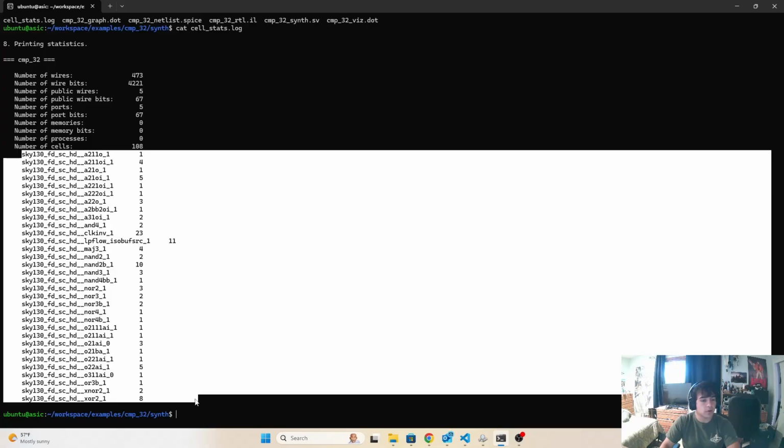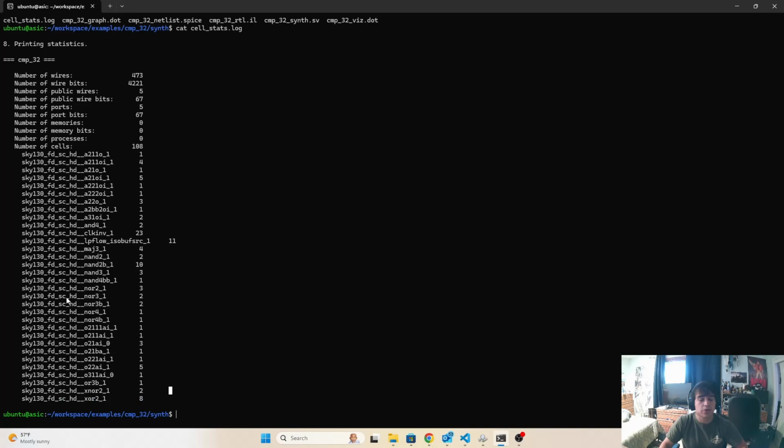In the future, these transistors all have powers associated with them, and so we want to see again what the power of each FET is going to be, or each device. And then we can essentially map all these numbers to power and calculate what our power draw is. So as we design, we can keep a close eye on what the power cost is going to be for our design, and feed that to the verification team and help them make decisions.